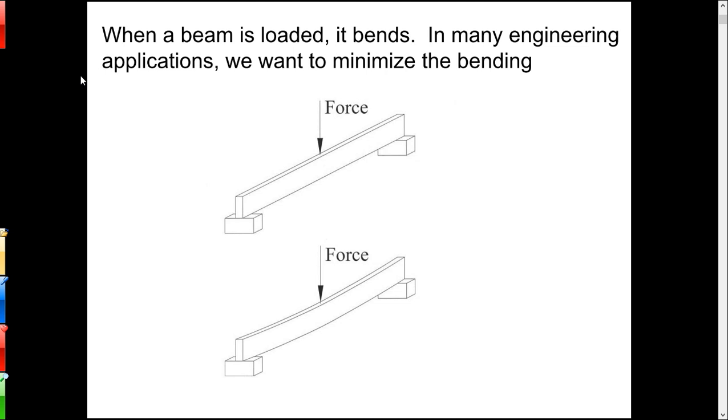So area moment of inertia is more of a type of resilience, where mass moment of inertia is more of a rigid body. I think of them in terms of what they represent and why we use them. Area moment of inertia I use when I'm designing a beam, because it'll help me determine part of the description of how well a beam will resist bending, which is quite often what we want to do.